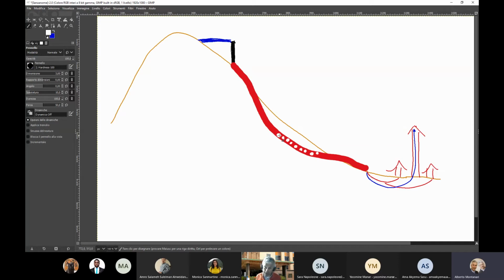And even the tap, when you open it in this condition, gets shocked, like a hammer shock getting into the tap. So you don't want this. The moral of the story in technical terms is that air in pressured water may give rise to what is called cavitation, and may strongly damage the pipe and any other tool that you use for water distribution. So you absolutely don't want air in pressured water. I hope it's clear.